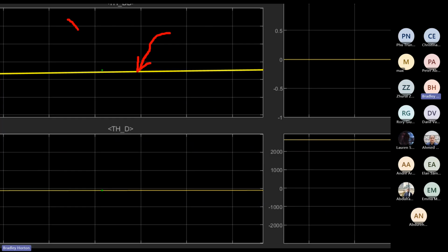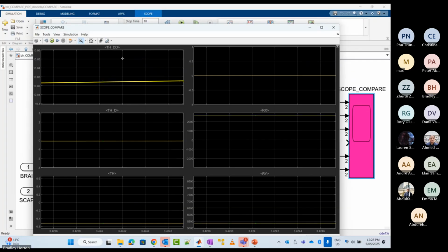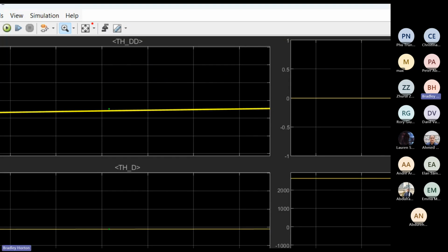But we've also got simulation results in the way of these green dots, and that would be from our green Simscape model. So the conclusion is that our Newton model is producing simulation results very similar to the Simscape model, which is quite reassuring. To bring the oscilloscope plots back to full view, this is the icon that you want to click on.